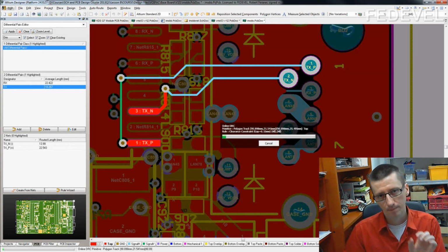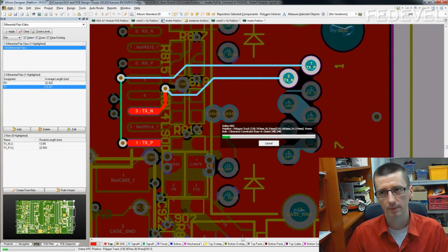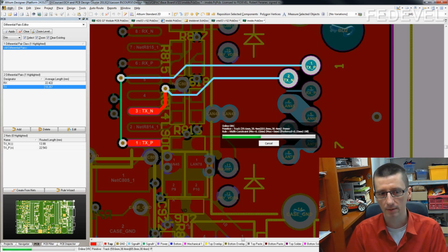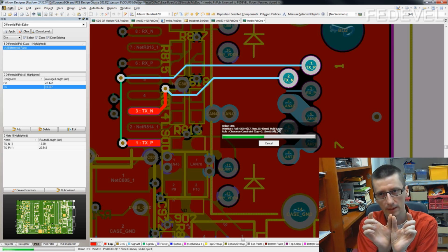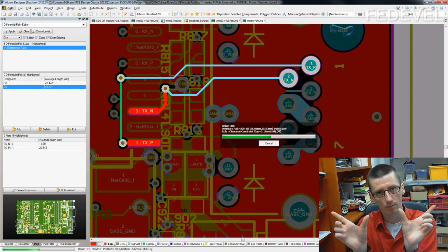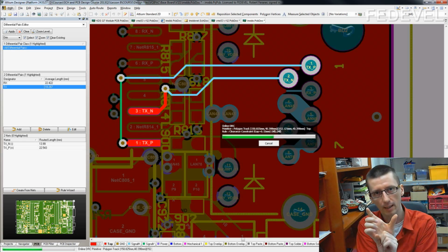Sometimes the gap is maybe better to make it wider, this default gap, because some differential impedances in total may be a little bit wider than minimum track plus minimum clearance plus minimum track. Some differential pair impedances have much wider track or much wider gap.